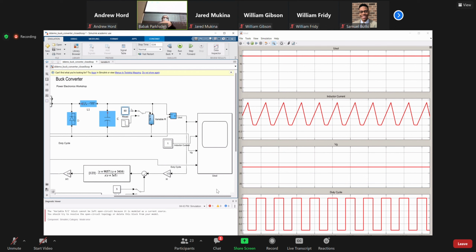So I'm saying that any converter during light load may go to discontinuous conduction mode, and you would have a different converter. Now you would ask, can I design a converter that solely operates in discontinuous conduction mode, or operates only in continuous conduction mode with defined boundaries?